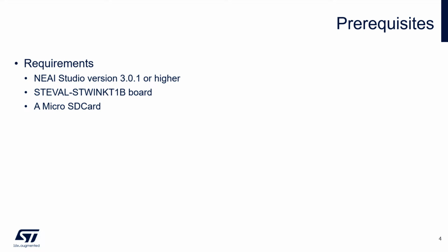The prerequisites for this section are quite limited since you only need the NanoEdge AI Studio version 3.0.1 or higher, since the data logger feature only appeared in the 3.0 version. You need also an STEval STWin KT1B board and a blank micro SD card.